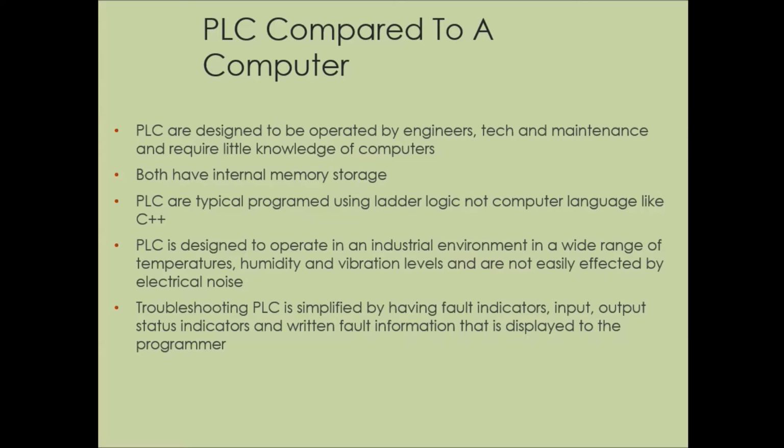A PLC compared to a computer. PLCs are designed to be operated by engineers, techs, maintenance, and require little knowledge of computers. Both have internal memory and storage. PLCs are typically programmed using ladder logic, not computer language like C++, which can be very difficult. PLCs are designed to operate in an industrial environment in a wide range of temperatures, humidity, and vibration levels and are not easily affected by electrical noise. Troubleshooting PLCs is simplified by having fault indicators, input and output status indicators, and written fault information that is displayed to the programmer.